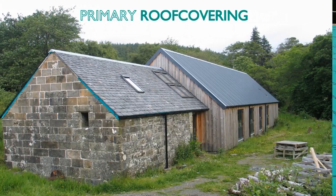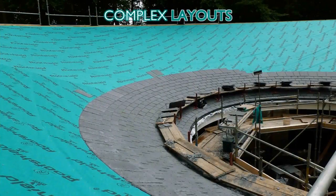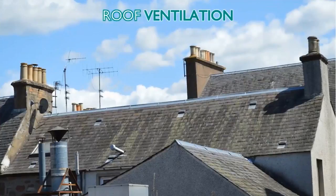Finally, the physical layout of the roof has to be accounted for, and particularly complicated roofs might pose problems when it comes to ensuring all areas are adequately ventilated and there are not dead spots where the moisture-laden air can accumulate and condense. Subdivisions of roof areas, for example for fire compartmentalisation, can further exacerbate this issue, as can specific architectural detailing of the overall aesthetic, which may preclude adding additional ventilation. BS 5250 details specific requirements for ventilating roofs and controlling condensation, and we'll move on to discuss that now.